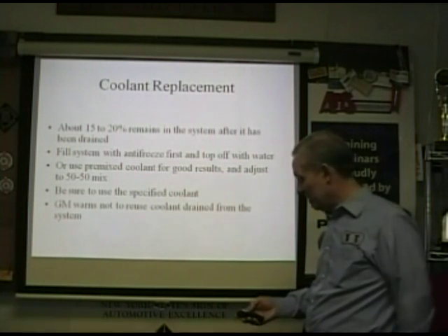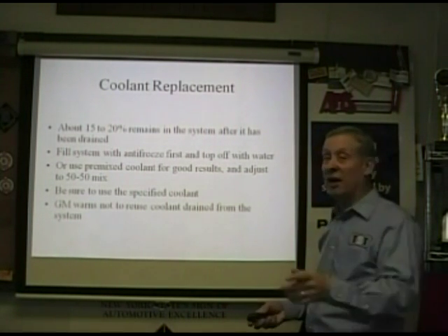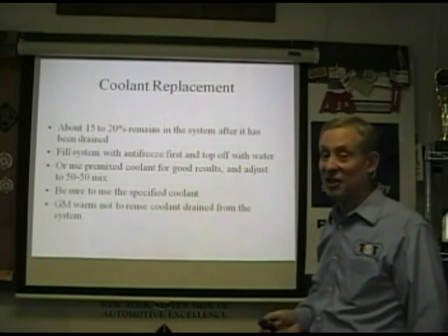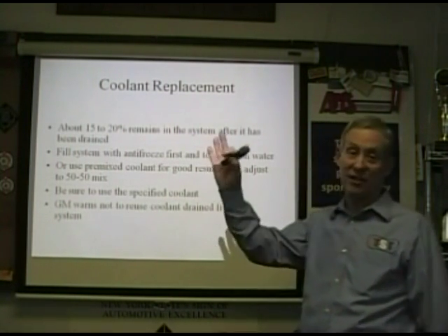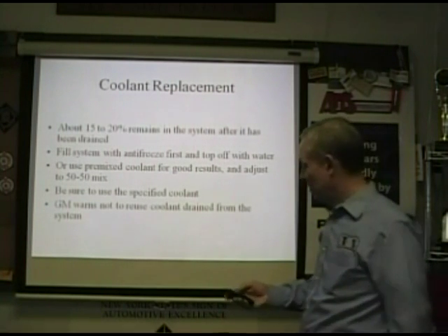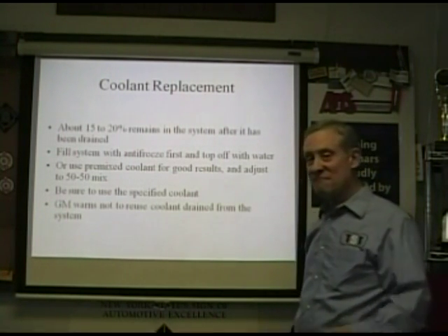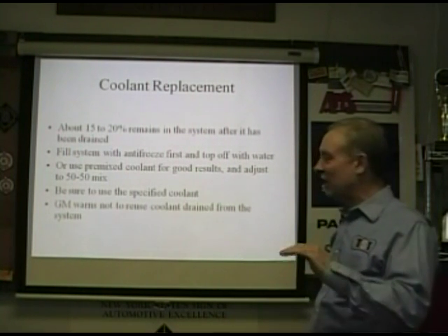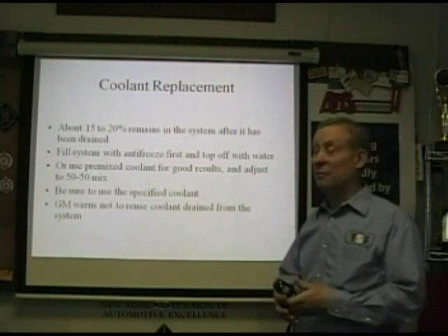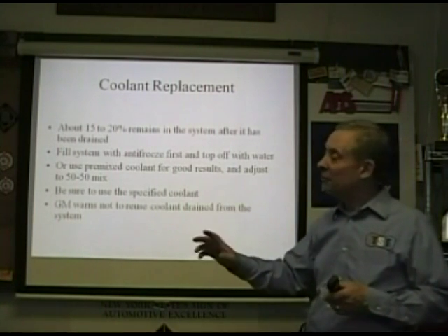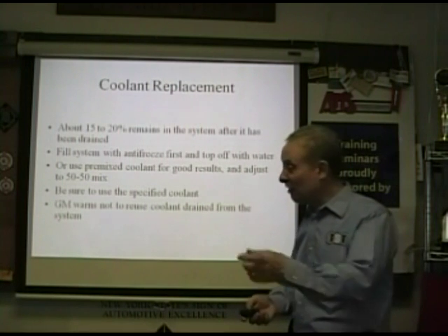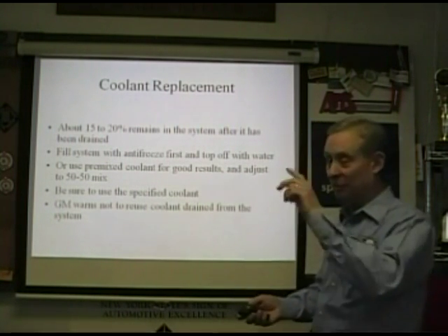Including the overflow bottle. And you have to then run it and purge any air, or use an airlift. You have to make sure that it's clean. If it's a system that's resistant to that, you may have to take it for a good test drive up a steep hill or whatever it takes. Crack those bleeders, and make sure you warm them up with that little electric heater nowadays. That works good. Whatever it takes. Run the air. The heating system may have an auxiliary water pump, so you have to make sure the heating system's turned on, because it may not run through there without that pump running. Turn the heat up max.